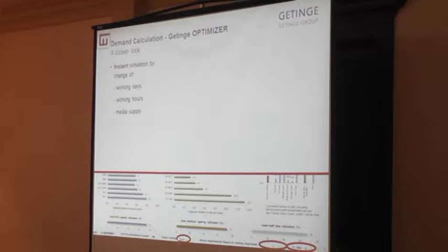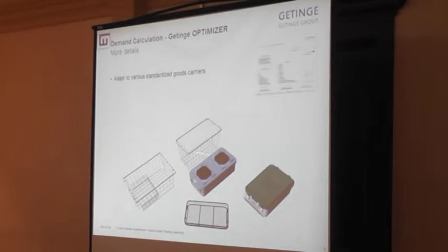The media, steam or electric heating, that's also changed. If I go from steam to electric heating, that is 10 to 20% of the washer effect. Then I need 10 to 20% more washers. That is seen directly in there. And I can also play around with the basket and container. Can go to the cart washer or washer. If I move the basket and container from the washer to the cart washer, much less washer is affected. So we can choose where they go to.